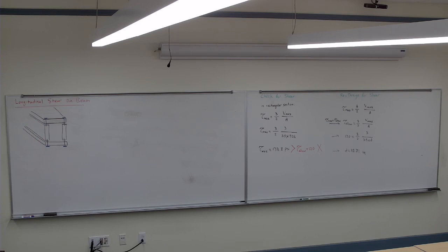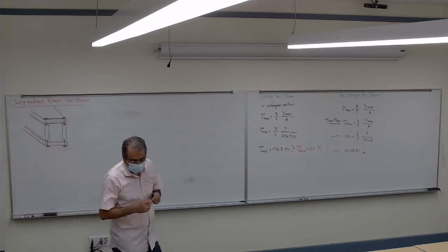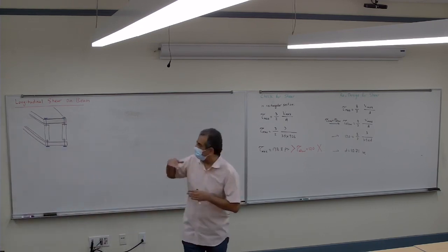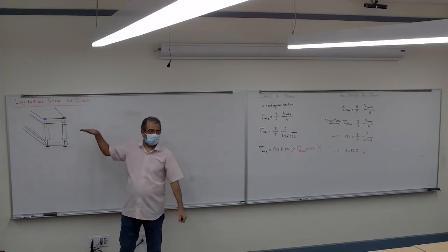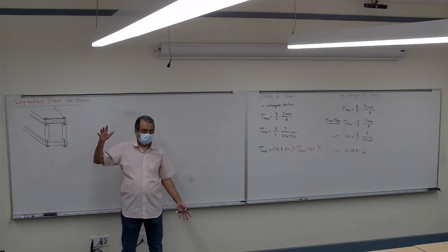Okay. So I want to see how much force is going to apply on those nails. Remember that any place, any time that I want to see how much force is applied on any surface, I have to cut it at that surface and disassemble it from that surface.